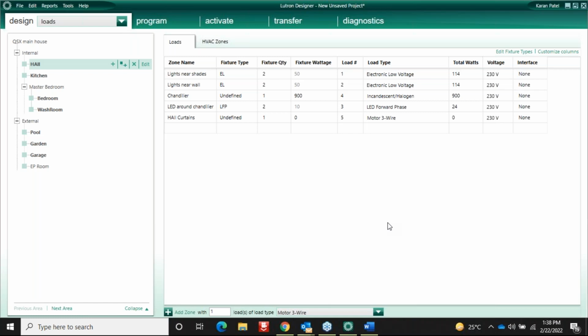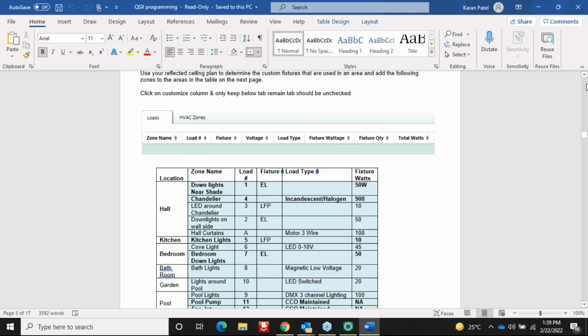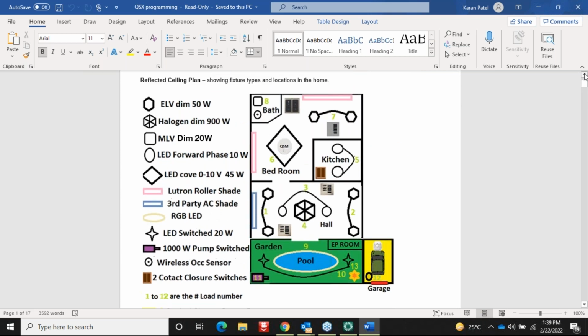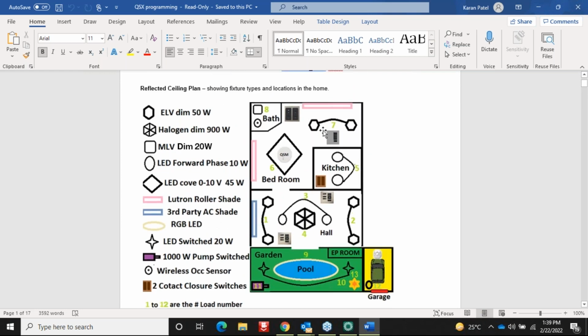See, I will tell you one thing. What happens when the electrical contractor does the installation is they give a name for each and every electrical circuit. For example, if you have a big villa, they will give the name for every circuit, like 1, 2, 3, 4, 5, 6 up to 13 or 14 circuits, or maybe 100 circuits. Now when you have the dimmers, let's suppose you got 5 dimmers. On the first dimmer you will connect 1 to 4, 1 2 3 4. On the second dimmer you will connect circuits 5 6 7 8 9. Dimmer number 3, 11 12 13 14.